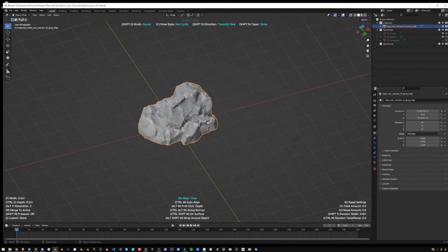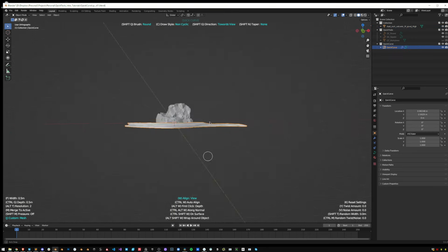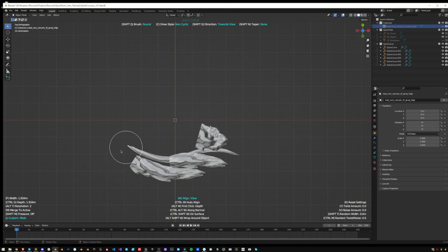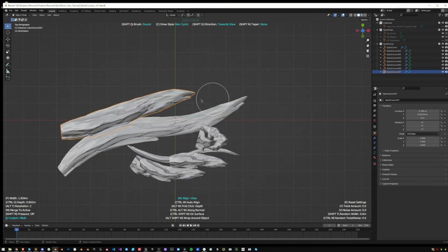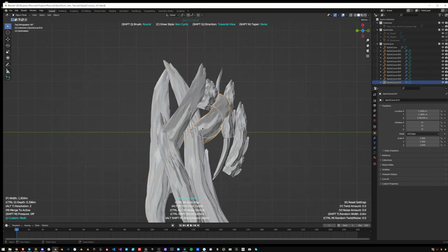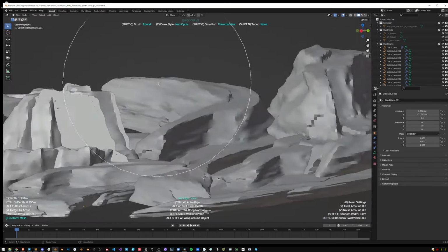We redesigned the custom object workflow from scratch. So one of the things that you can do now with this new system is, as you saw in the Control D menu, you set the mesh array offset to 0. And basically what this is going to do is just stretch the custom object that you're drawing with completely along the curve, as opposed to arraying it multiple times. So what that opens the door for is basically drawing with an object as a custom brush.